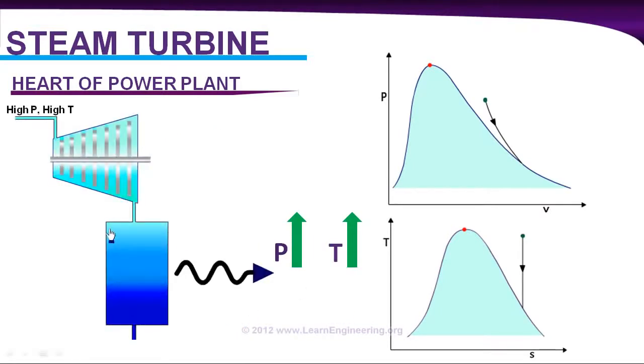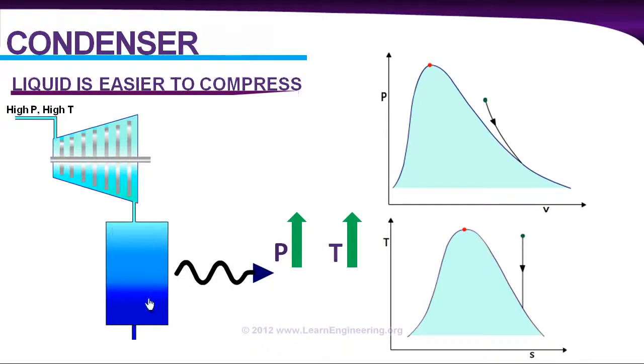Like this. You put a condenser over here that can reject heat to the surrounding. So vapor will get transferred into liquid state. Now this process can be drawn in PV and TS diagram like this. And during heat rejection there is no pressure change because fluid is free to expand. And obviously this is a phase change, so temperature cannot change.